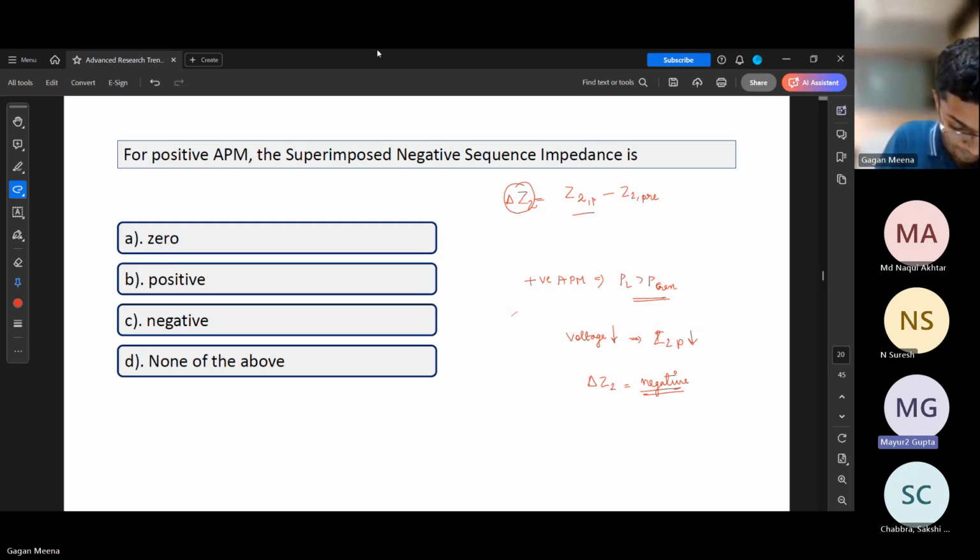Active power is an attribute of frequency rise or drop, and reactive power is for voltage. That's what I'm saying: active power depends on both voltage and frequency. But in the transmission system, the decoupling is very prominent. In the distribution system, because of the inherent nature, the R by X ratio is quite large as compared to the transmission system. That's why decoupling is not possible here.